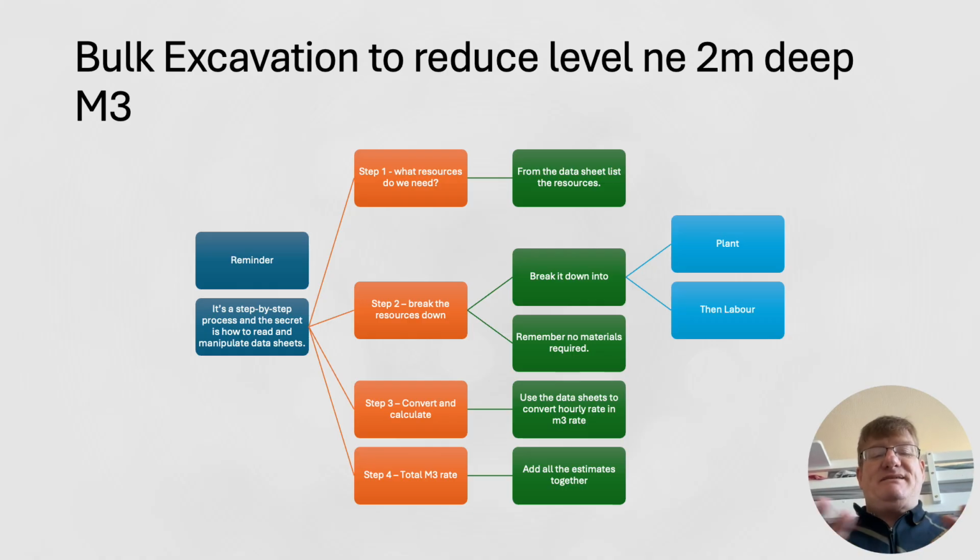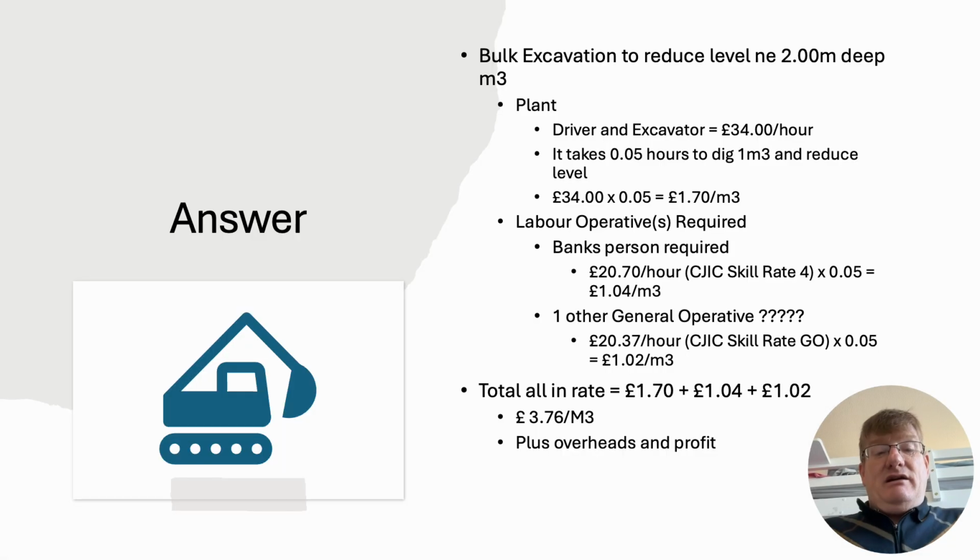Then the next thing we've got is this bulk excavation to reduce level, not exceeding 2 meters deep. We're not going any further than 2 meters deep, and in this particular one, I've broken it down for you. But if I look at it in more detail, again, don't forget, first thing, what do I need? Well, again, I need an excavator, an operative, a banks person.